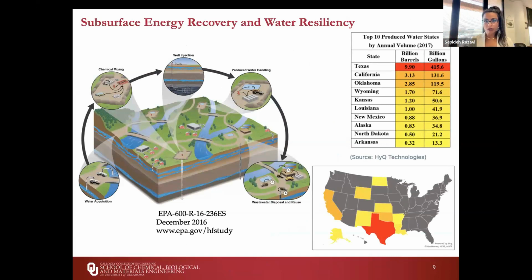So when we want to get oil out of the reservoir, oftentimes water flooding is being done, where water in conjunction with additives such as surfactants, which are used to reduce the surface tension and help with the mobility of oil, and particles that are used as proppants are added. And then once the oil is removed on the other side, the water is going to come out with all these additives, surfactants, particles, and therefore this produced water has to be dealt with.